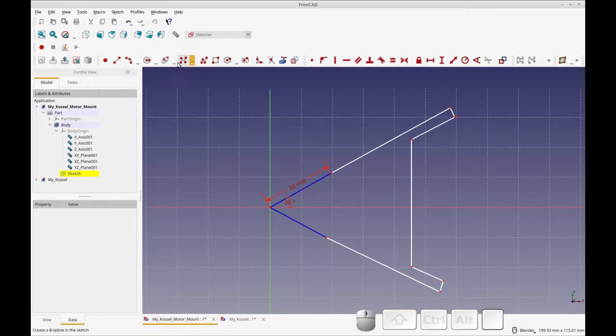Now I'm going to draw the inner shape, again using the polyline. And this is where the motor shaft protrudes and the timing pulley resides. And also I'm going to just kind of shape this a little bit better. Now I'm going to add the filleted radiuses for these corners by using this tool. It's create a fillet between two lines or at a coincidental point. So we're using the coincidental point. Okay, I'm going to leave this unfilleted because we're going to do that at the end.